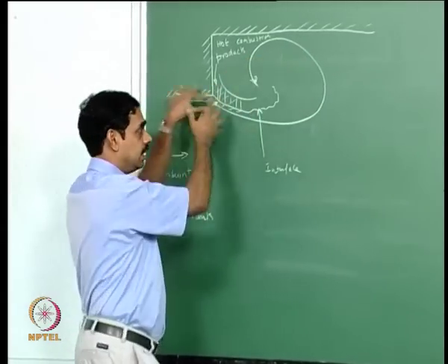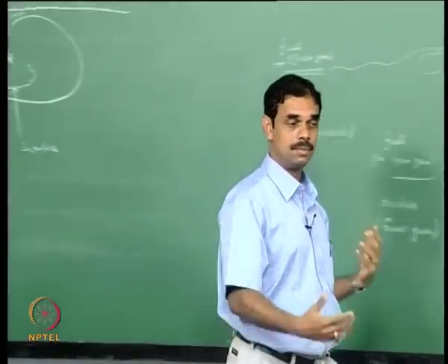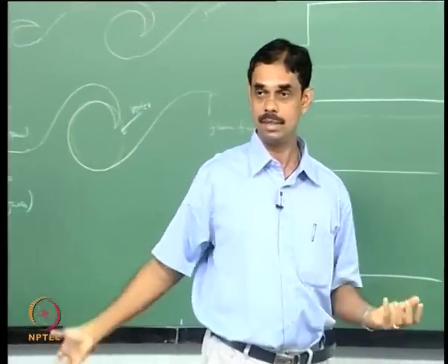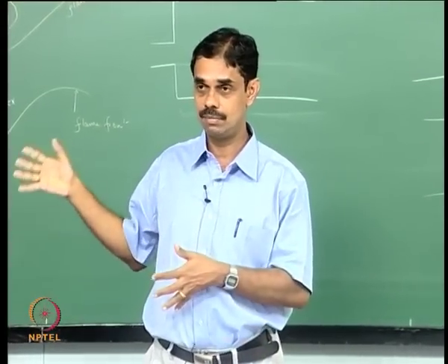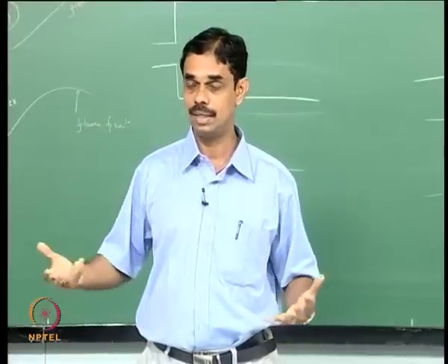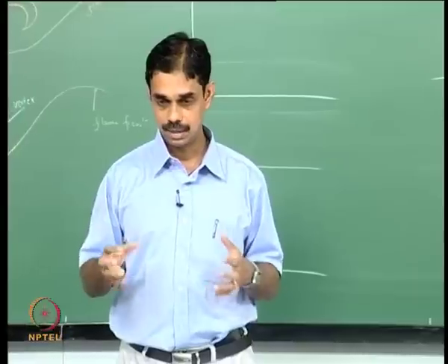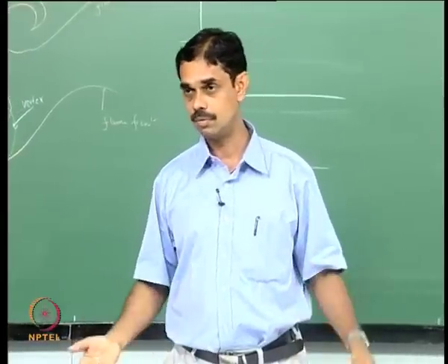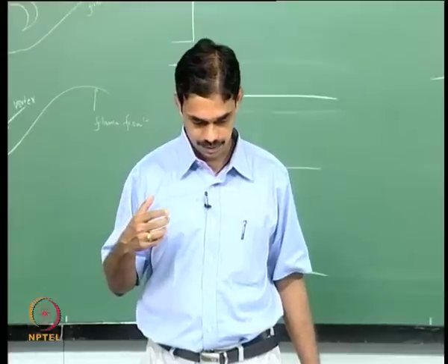burns very vigorously, then again this phenomenon happens, and all the things that we studied about how the acoustic model has to be developed will again apply here, and this time delay between the fluctuations here and the heat release will clearly affect how the reactants are going to burn, whether they are burning in phase or out of phase, and therefore whether they are going to drive the instability or damp the instability.